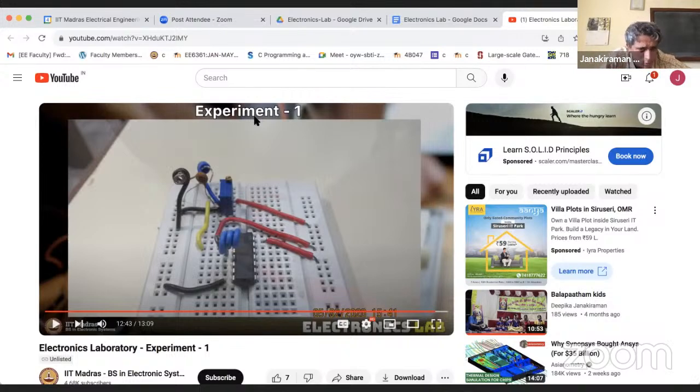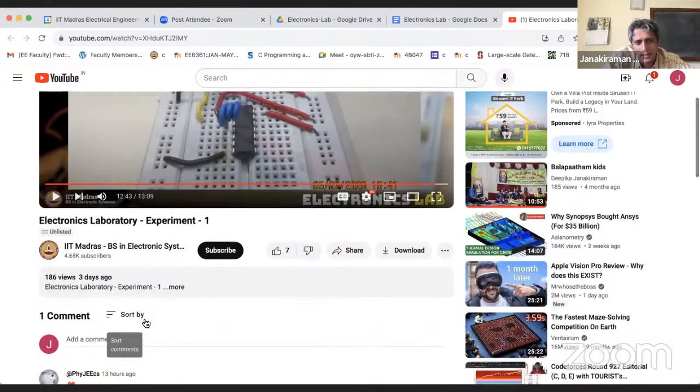Connect the 5-volt supply to the potentiometer to this red color part here, and ground to the black color part here, and then vary the potentiometer using a screwdriver and measure the output voltage using the ADALM 1000 kit. That is very similar to what you did in your electronic systems and systems thinking lab. So that's about what it is.